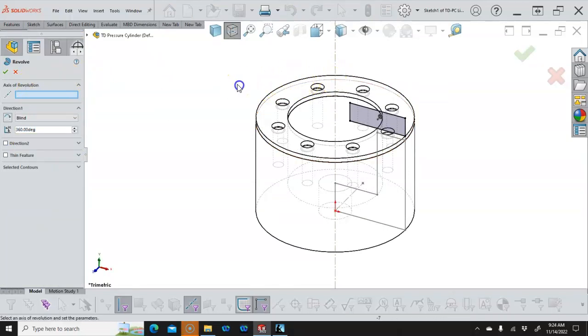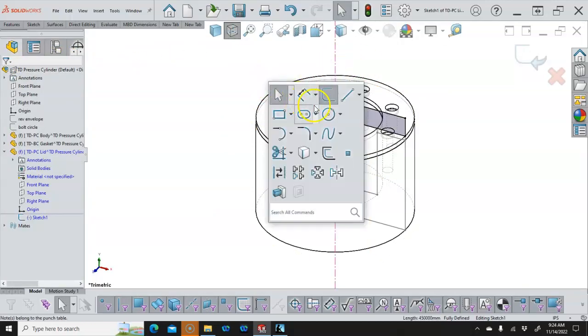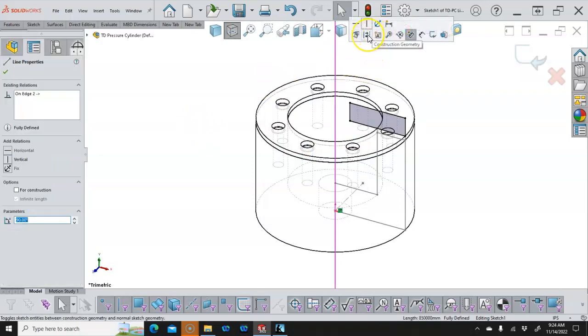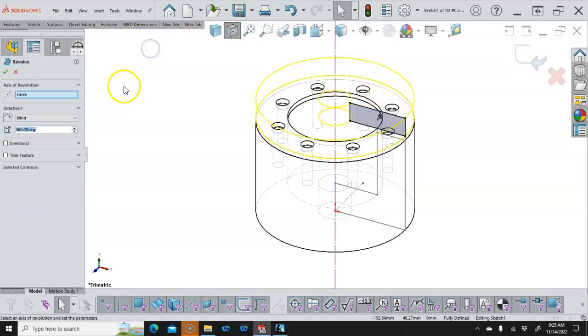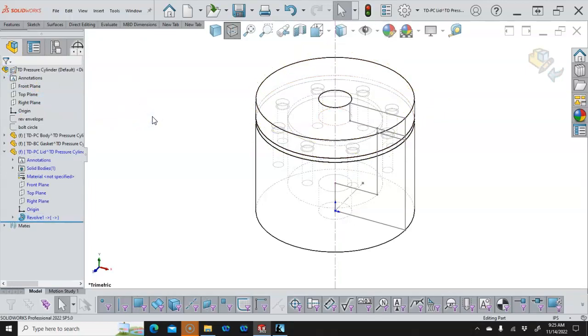I didn't particularly like that. Right, so it's not. It wants a local sketch center line. So we'll convert it, do the object. I could always go into the line, make it construction line, center line, infinite length vertical, and attach it to the origin. Or I can convert the one that's there. Since we're doing all of these conversions, I can also use the existing. All right, so when the lid completes, then that's fine.